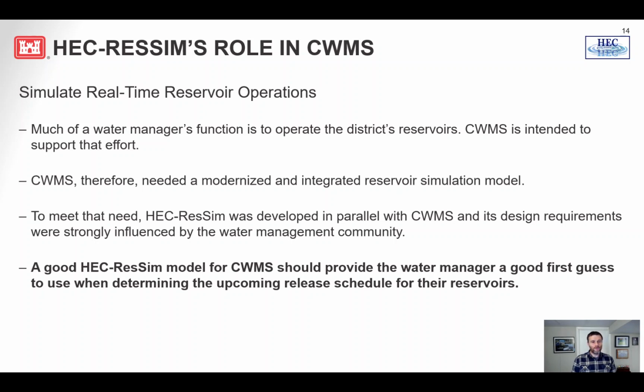So there are a lot of tools that have been added to ResSim that are very specific to SWMS. One of those things is release overrides and the operation support interface. Just the concept of a release override is very specific to SWMS. If you were doing a study, doing release overrides is kind of considered a no-no. You have to have all of those rules defined in an algorithm to do your analysis for a study. Whereas in SWMS, we very much want a water manager and their brain power involved with the computational process, so overriding releases or a pool elevation target is very much integral in this part of it. So that's really the main difference that you would see from ResSim within SWMS versus in a study environment.